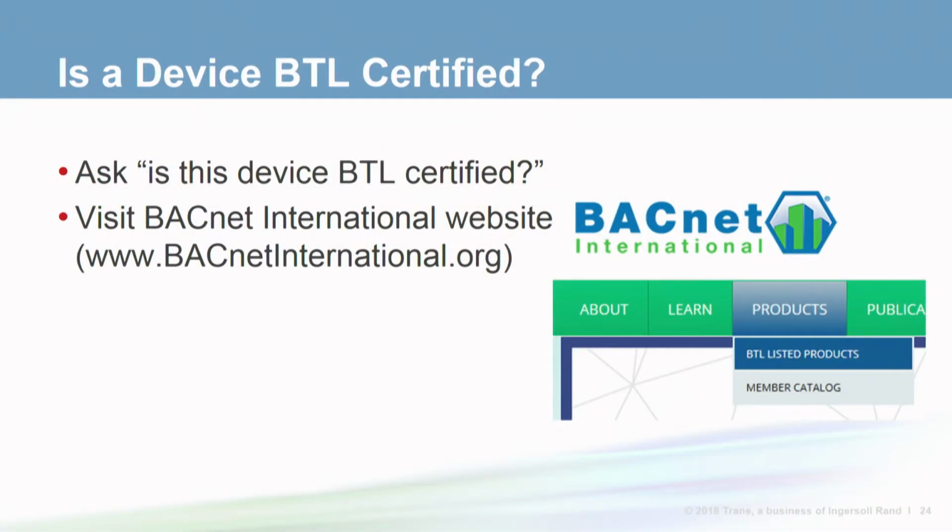BACnet International maintains the official list of BTL certified devices on their website. On this site, you can click on the BTL listed products from the menu and access this list. Once you find the device in the list, you can view the protocol information conformance statement.